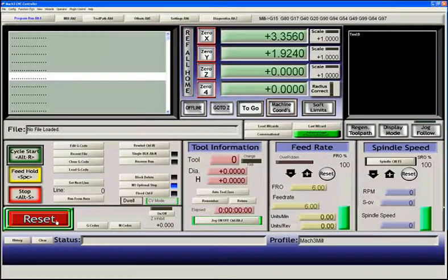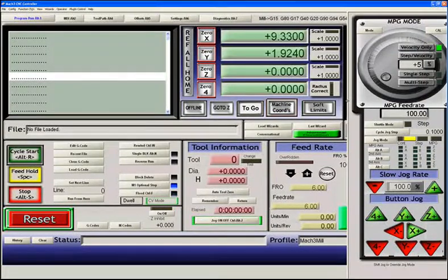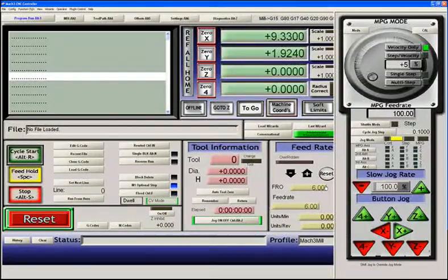Now a secondary complaint is, okay, my motors move, but they move very slowly when I jog. Why would that be? Well, as you can see, if I hit jog, I'm going to 120 millimeters per minute on this system. If I hit the tab key to bring out the jog tab, and incidentally, to control the jog tab, drag it out so that it is on your system facing you and you can read it fully, tab it in, tab it back out, and it will remember its location from then on. The jog rate down here at the bottom, you can see it's set to 100% on mine. That can be set to any value, so make sure that it's set to a value that you want it to be for your slow jog.